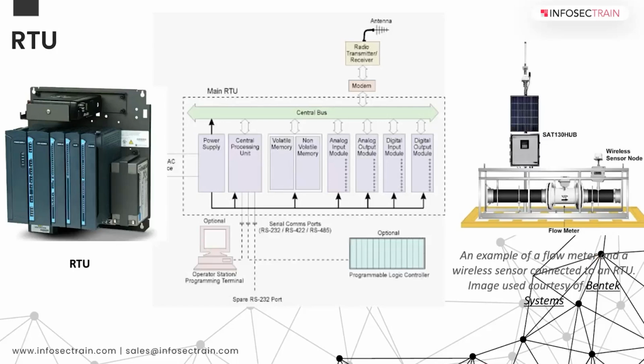All right. Those three were the most important controllers that you need to know when we talk about cybersecurity, especially industrial cybersecurity. But there are some other hardware and devices that you still need to know. One is the RTU. This is a very simple one, where you just have the IO module, and this is being transmitted using serial communications to a PLC. This could be received by a radio or a LAN or something, and this is the basic structure.